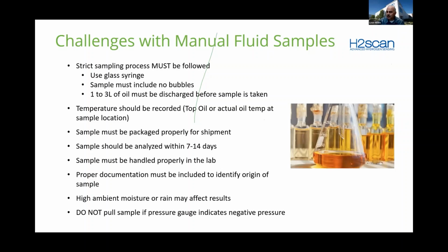or again, pull atmospheric gas into the transformer. I was at a power plant in Texas one time, and a customer said, in the winter, we open the valves on these transformers and the oil doesn't come out. We don't understand why. I looked up at the pressure gauge and I said, you need to add some nitrogen pressure to that transformer, and you should not be opening those valves when the transformers are in negative pressure. So these are real things that happen,